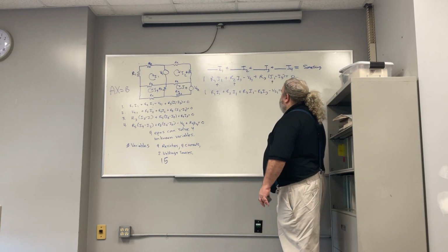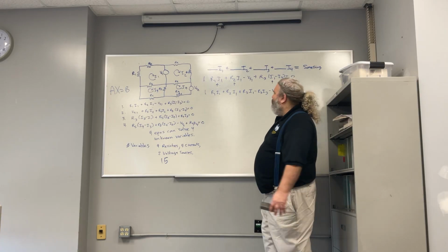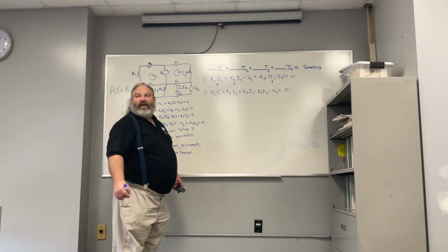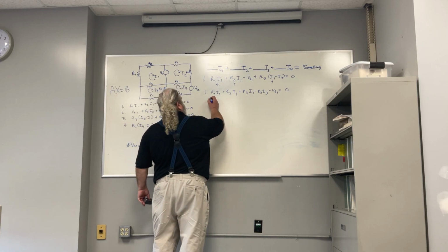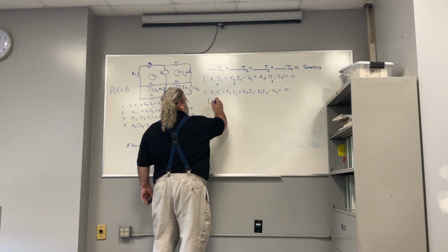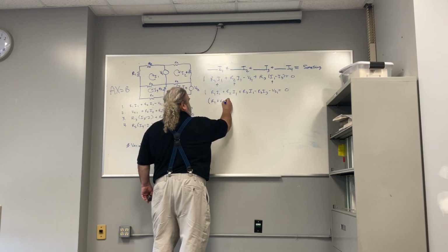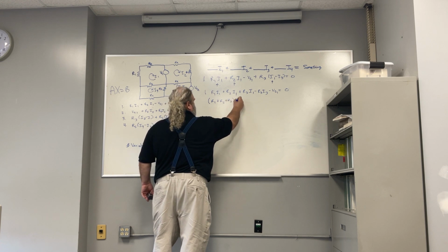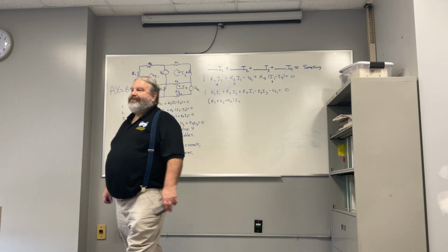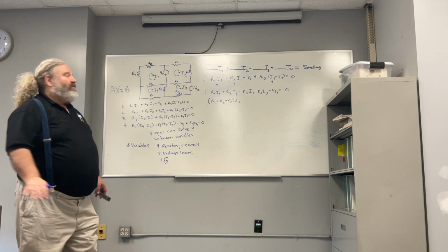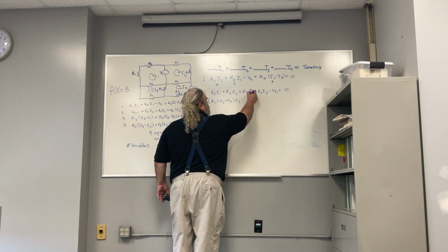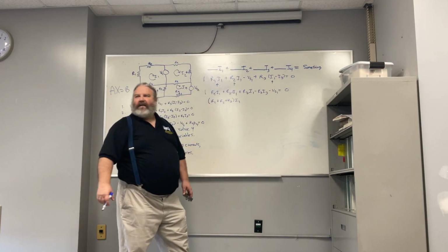So Quinlan, what am I going to do now? I want the coefficient for I1. What is the coefficient for I1 then? Coefficient for I1 would be R1 plus R2. So I'm going to put R1 plus R2 in parentheses. That is my first coefficient in A. Everybody see that? Now, it's bookkeeping. So what I like to do is I'll put a little thin line, and I know I've taken care of those. Got it?